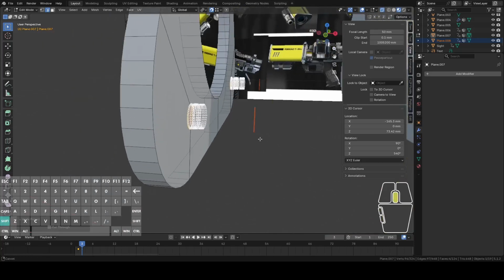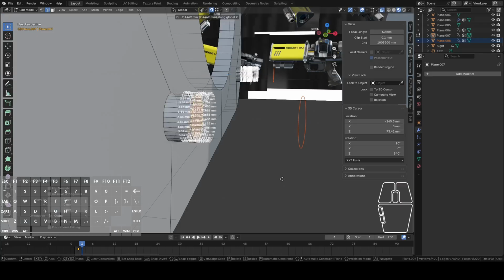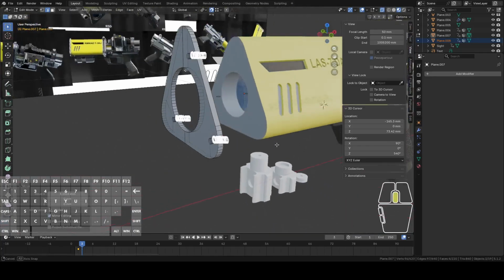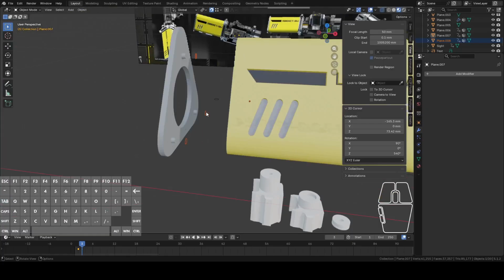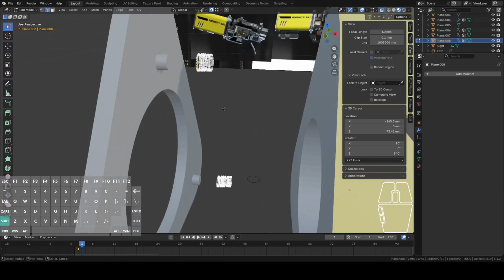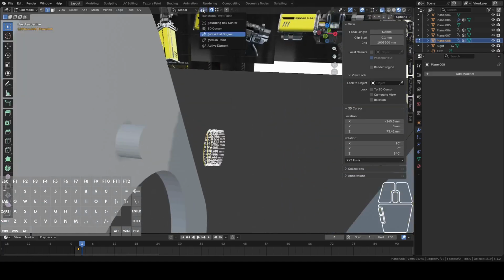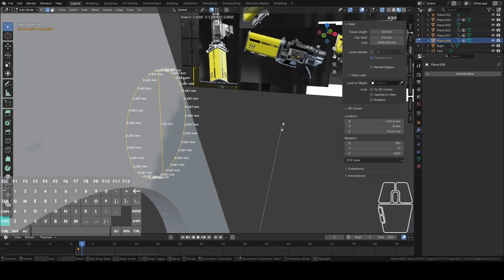And let's take these and protrude them, say 5 millimeters. It's plenty. More than enough, I would think. And now we gotta size these up a little bit to make the other holes. So with individual origins still on, let's go up to 7.5.